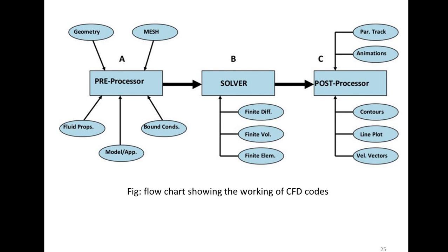Boundary conditions are what's outside the boundary, where there is a wall, where there is a solid, what is the pressure at the inlet, what is the velocity at the inlet, all sorts of things that you know about the thing you want to study.